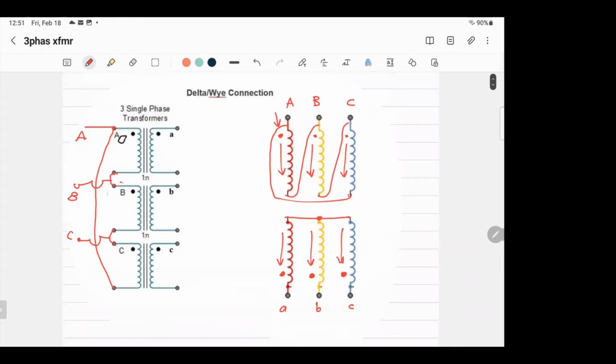Another thing, remember, every single transformer has one coil. What does it mean? It means if the current goes in this coil and the current goes there, there will be a ratio, one is smaller or bigger in number, but they are in phase. If this current is at angle 0, this current is at angle 0. If this current is at angle 30, that will be 30, because they are in the same coil, with the same flux linking them. So the current will be in phase.